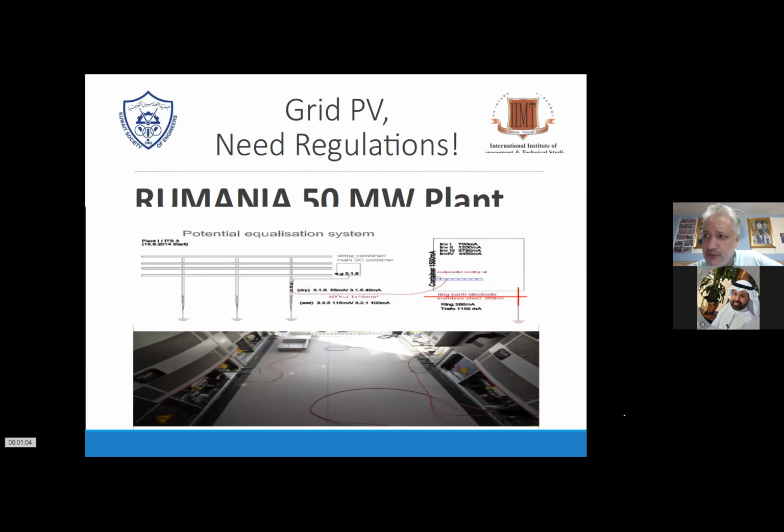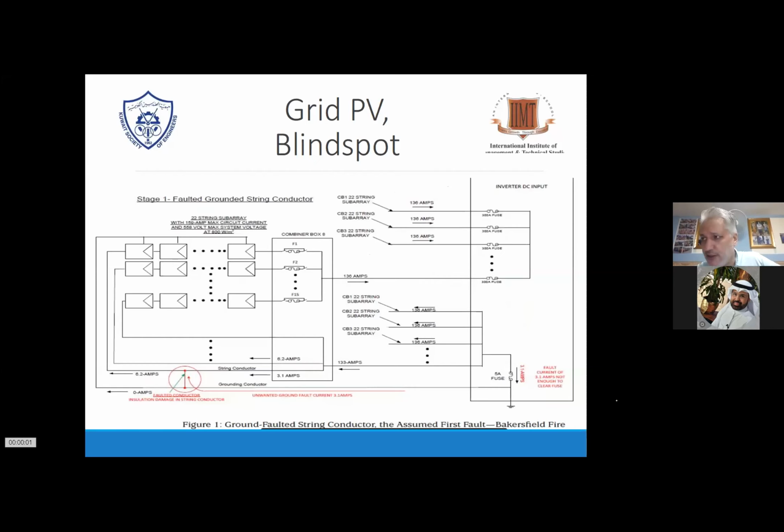So what happened was that one of these inverters out of a timer-based string will be the master, and then the more the system comes online, the more slaves will switch on. This was totally switched off, so the whole system was running during morning and nighttime, very inefficient. So the earthing was actually enough to get it back to master-slave. Those are the blind spots, which we always say.